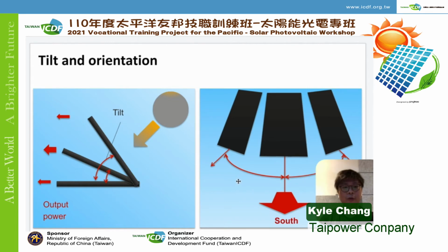Let's change the horizontal and the tilt. It's very important to have lots of direct sunlight. And like I mentioned before, the more direct sunlight the module receives, the more energy is converted. Other effects play a quite important role: shading, and the temperature effect on the module efficiency. And that can have a significant effect on the performance of a PV system.